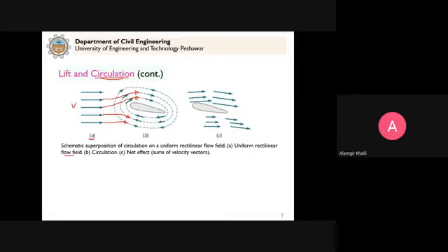So now there is a circulation and the fluid flows past this object. You can see that the velocity vectors here and here are in the same direction, so they add up. That's why V increases. This is the reason that V increases at the top of this object.